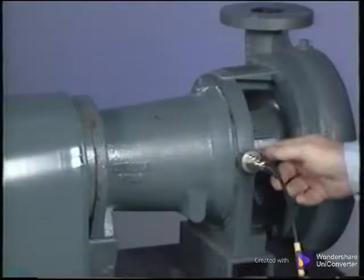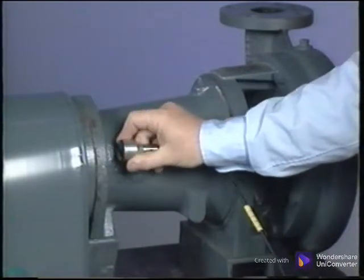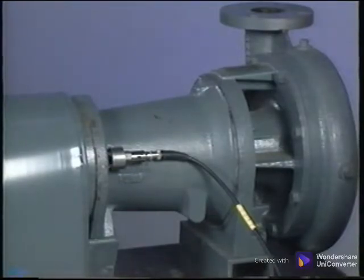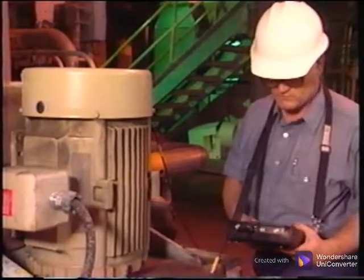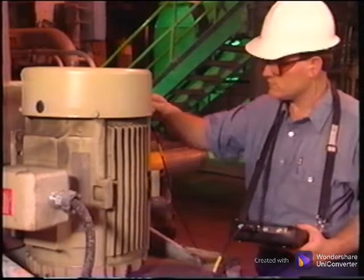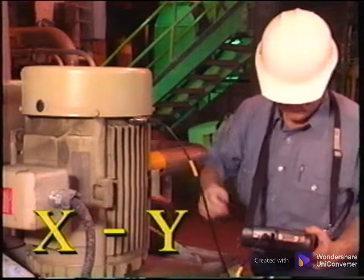Axial measurements could be made at either end of the pump, but the impeller end tends to show energy due to flow, which can mask other problems. The same criteria apply to vertical mounted pumps and motors: 2 radial readings at each bearing location and at least 1 axial reading per shaft. The radial readings should still be 90 degrees apart, but should be called X and Y direction.